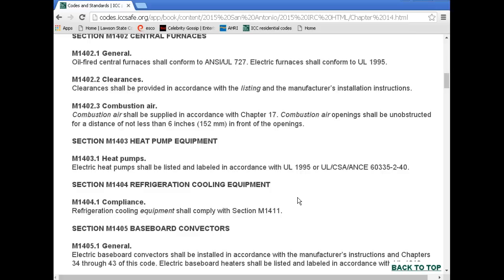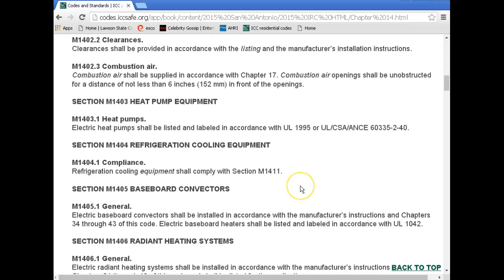So in other words, if I have a 3-ton heat pump, 36,000 BTUs, then for every 1,000, that'd be 36, I want 6 square inches. So 6 times 36, the return and the makeup air, the fresh air, would have to be at least that. So I cannot believe we're not going to see that again, okay? We'll have to keep our eyes open. Y'all have to help me. I don't know where it is. It's going to be in here.